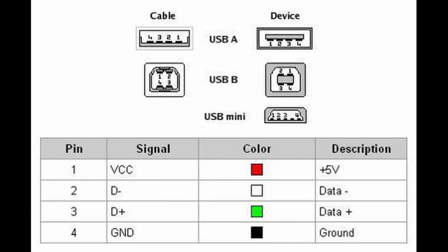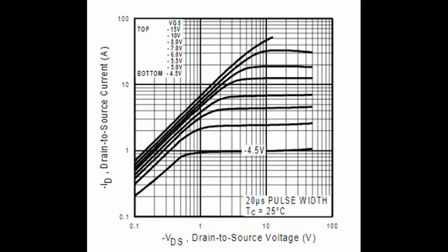The 3 MOSFETs are P MOSFETs, model name IRF9530. From their output characteristics found in the datasheet, we can be sure that the sources of all of them are connected to 5 volt and the gate is connected with the 4017. The drain is connected to supply power to the green, red, and yellow LEDs all over our model.